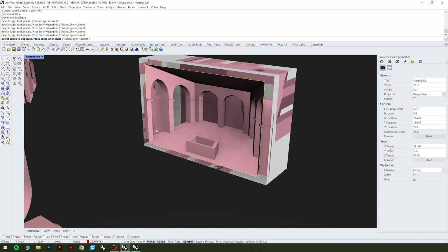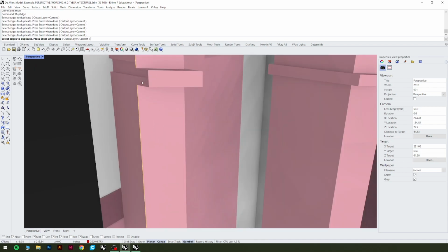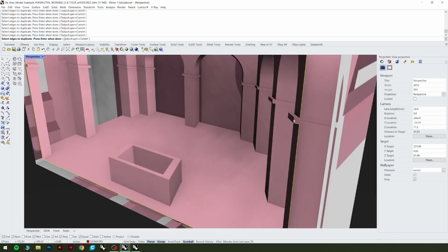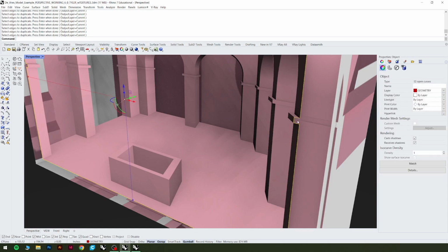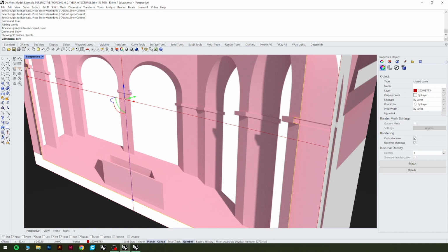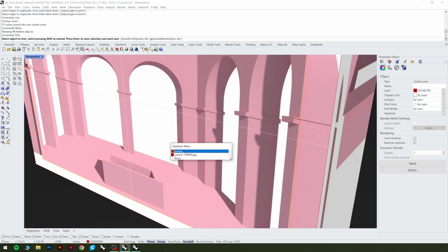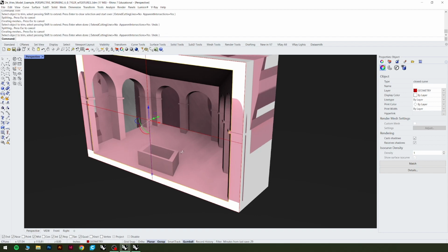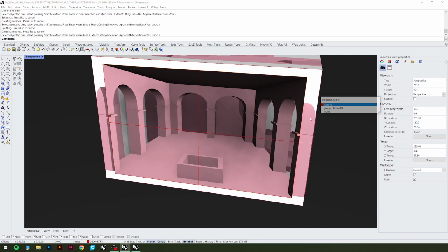I think there's a way I could have had it do the chain edges. I don't know why I didn't do that. Here we go, select all those, join, type in show, while that's still selected, hit trim, select object and trim, and we'll trim this surface. Was it the right one? I'm not sure. Okay. Here we go.